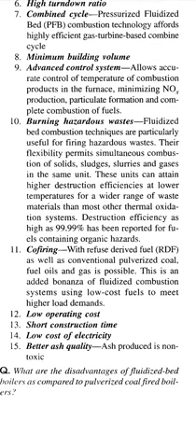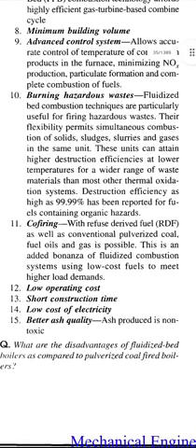Burning hazardous waste: fluidized bed combustion techniques are particularly useful for burning hazardous wastes. Their flexibility permits simultaneous combustion of solids, sludges, slurries, and gas in the same unit. These units can attain higher destruction efficiencies at lower temperature for a wide range of waste materials than most other thermal destruction systems. Destruction efficiency as high as 99% has been reported for fuel containing organic hazards.